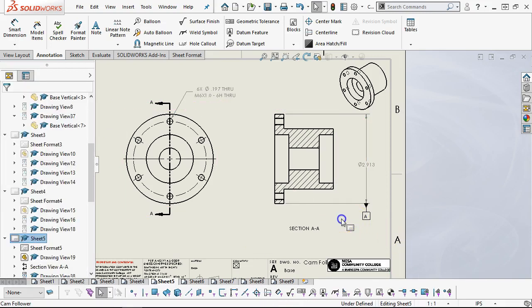Oh, I like how that one applied since it was selected. All right, and then the runout. And this is not the rotating part. Usually I would think of the rotating part, the shaft, having the total indicator runout. So I will give you the option of putting the bearing faces as positional tolerances or as runout tolerances. One of the reasons that I made this part round though was for ease of manufacture, so that we would be able to fit it into the vertical component fairly easily.